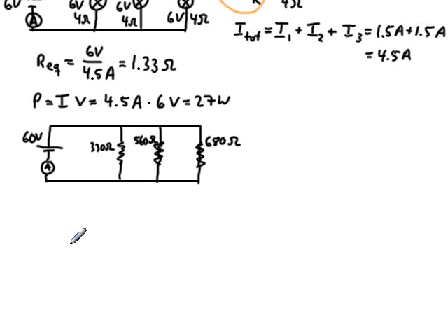Okay, the same rules would apply. Each device connects to the same 2 points of the circuit. The voltage is therefore the same across each device. So actually that one we do know, 60 volts across each one of these. Okay, then the current divides among the parallel branches. Ohm's law applies separately to each branch. So each one of them is going to get some current.